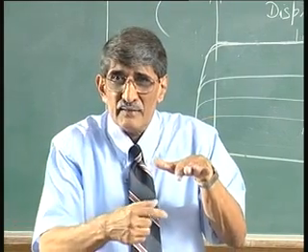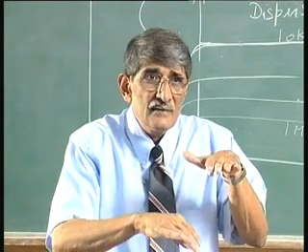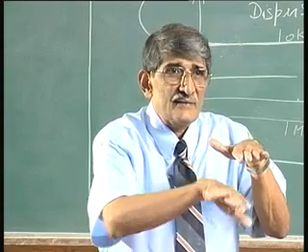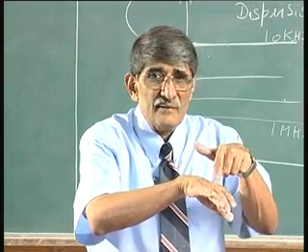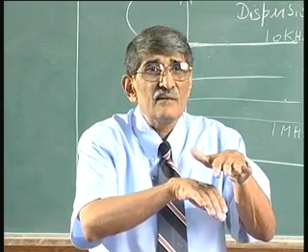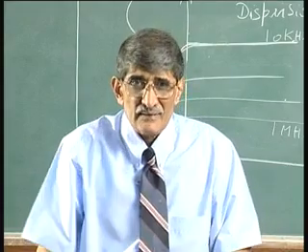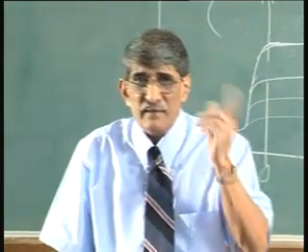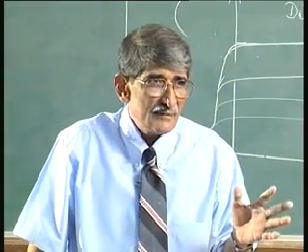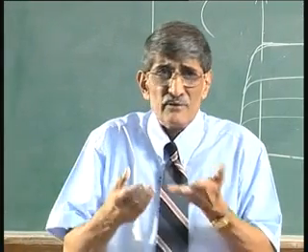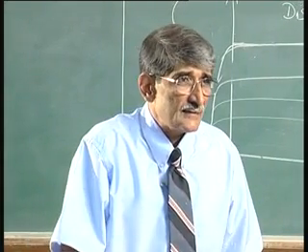But now what is happening is, channel charge is not responding because it is shielded by this interface. So, response is by the interface. When the interface responds, the drain current is not changing. So, delta ID by delta Vg is small. That means transconductance is small. That is what you are looking for: a very high transconductance.